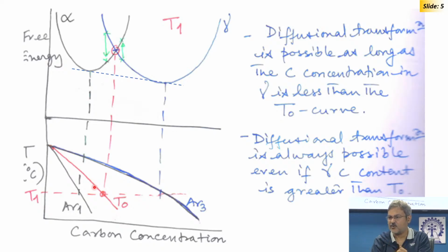You will see how much shear strain is involved. So, a lot of strain, a lot of interface will be produced, dislocations and twins may need to be produced to get this kind of features. So, this entire energy can be quite high, 700 joule per mole, something like that.